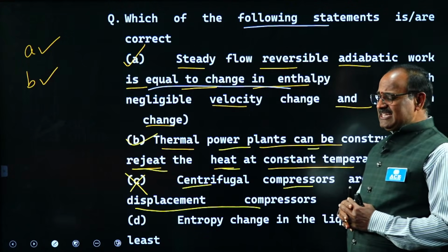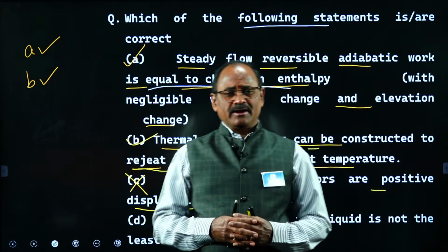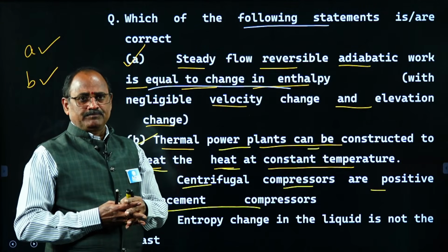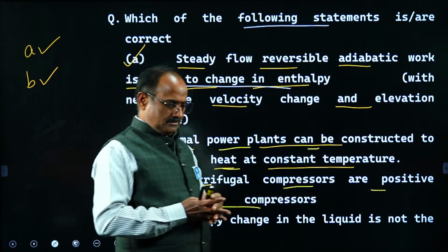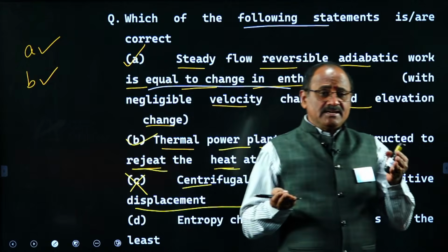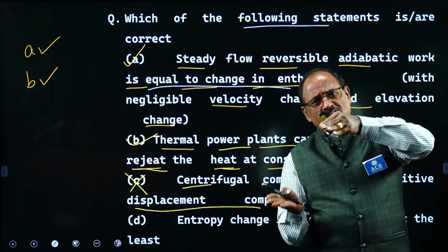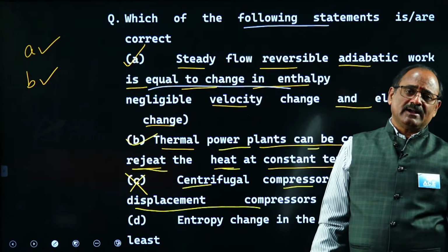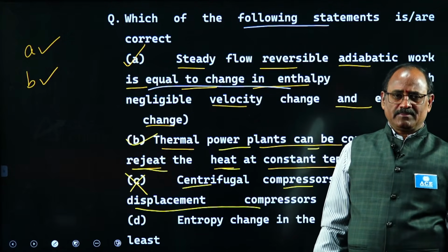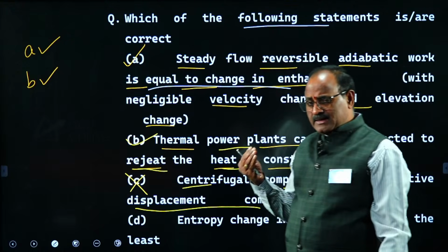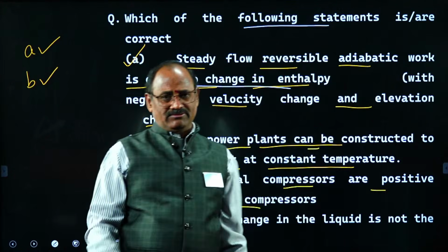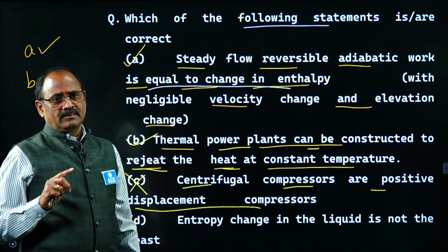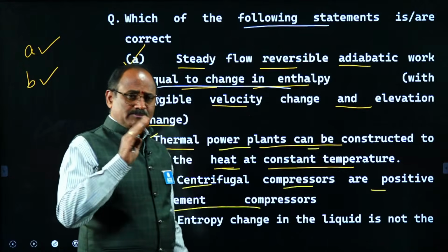Whereas in our reciprocating compressor, the pressure increases by reduction in the volume of the material. That kind of compressor, in which the pressure is increasing by either reducing the volume of the material or by the backflow of the receiver gas, comes under a positive displacement compressor. In the Roots blower, pressure is increasing by backflow of the receiver gas. That point we clearly discussed in the classroom. So, Roots blower comes under positive displacement compressor.